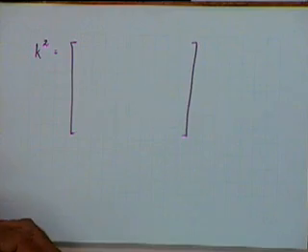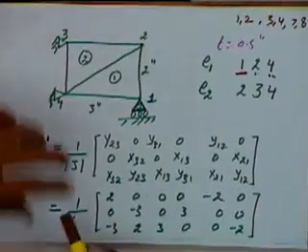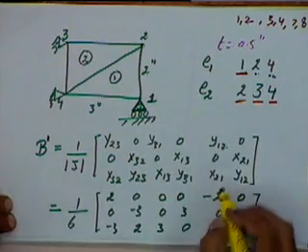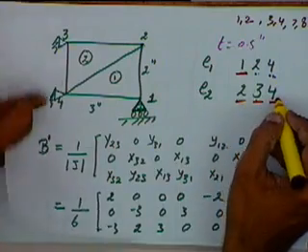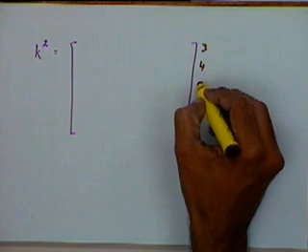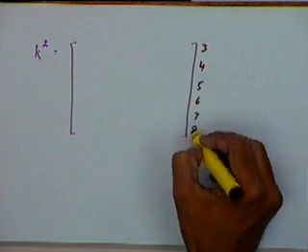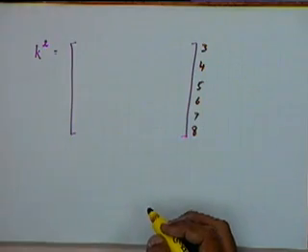that will again be a 6 by 6 matrix, and the second element is defined between nodes 2, 3 and 4. So the global locations occupied will be 3, 4, 5, 6 and 7, 8. So this will go to global locations 3, 4, 5, 6, 7 and 8.